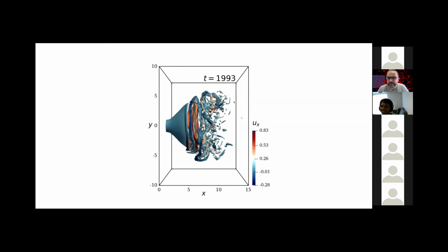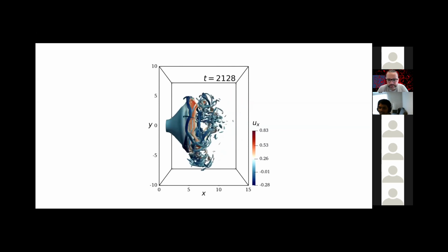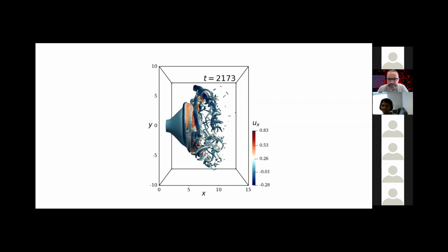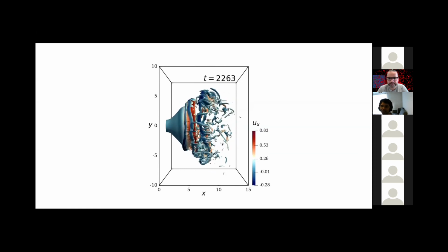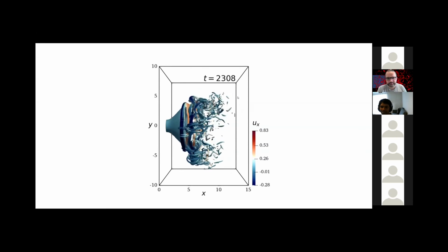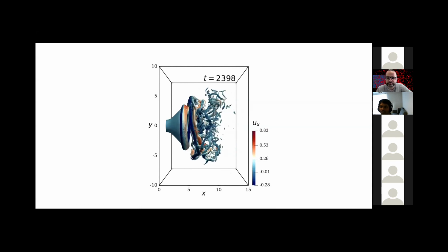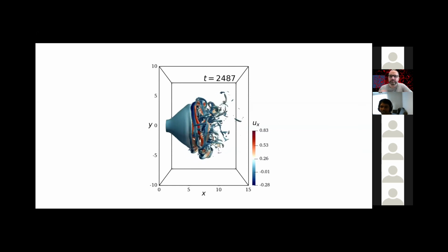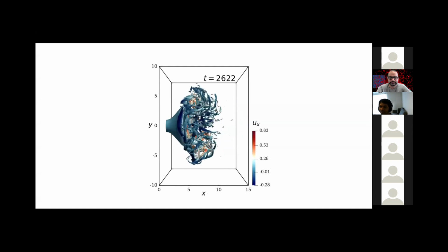And one final question from Arash is, how do you initialize the simulation? What is your initial condition? That differs depending on whether I'm doing a hysteresis study or not. If I'm not doing a hysteresis study, I'll take a streamwise invariant initial condition, also known as columnar initial conditions. If I'm doing a hysteresis study, I'll start from a given flow state. I'll start from a bubble form, and then I'll change my inflow slowly and so on. The initial condition is an already existing vortex breakdown state.